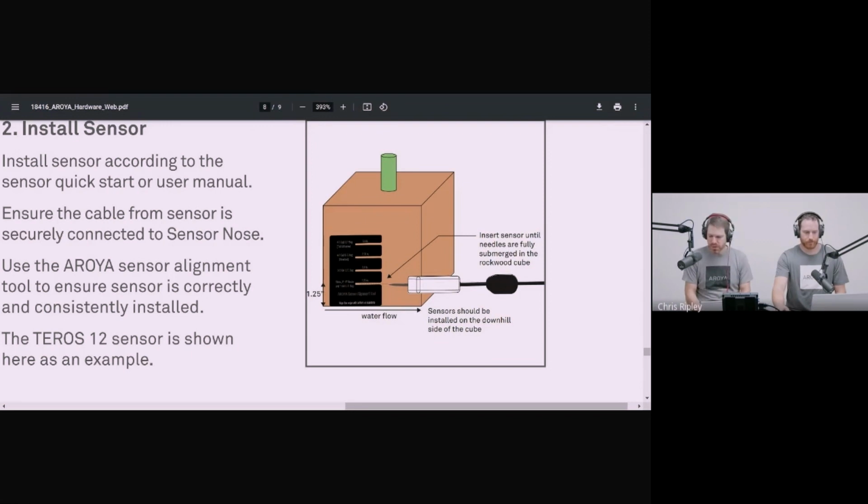Yep, thank you. Let's go to sensors reading 0, a 0 EC sensor. What does that usually mean? So if we're looking at 0, it could be that there are absolutely no nutrients in the solution. One of the things I like to keep an eye on is if we've got a really low water content, it could also mean that the EC is so high that we can't read it.